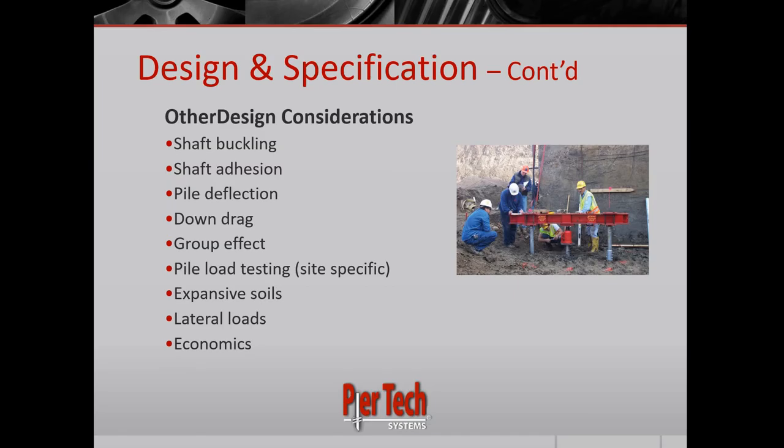And lastly, probably most important to make the project feasible is economics. So if you take all of these into account during your design, you can be very economical. Sometimes it looks expensive to have a soil report done, but it'll make the project cost less in the long run. Same thing goes with load testing. Usually the load testing will actually save you money on the project from an over-designed pile system.